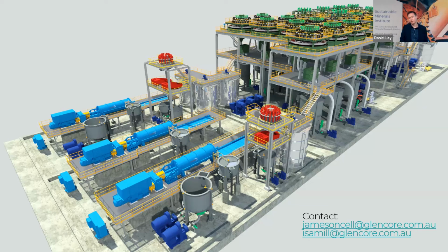The second part of the question was the IsaMill. What do you forecast to be the maximum feed size for IsaMills with 16 mil feed and associated energy reduction? Okay, that's very specific. I'd have to come back on specifically what it would be at 16 mil. But in principle, we're certainly trying to target well up to 700-800 micron as a feed. But as I said, it is an area of research. At this stage, our highest installed IsaMill is at 400 microns.